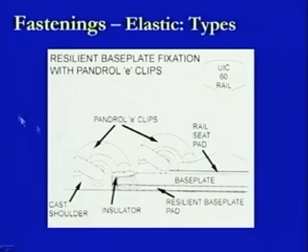In this one, what we are seeing is a connectivity of the rail section where the base plate is also being used. Now, when we are using a base plate, we can see that there are two pandrol clips which have been used here. One pandrol clip fixes the rail section on the base plate, and the load is being transferred at this location. That is how it remains in a fixed condition.